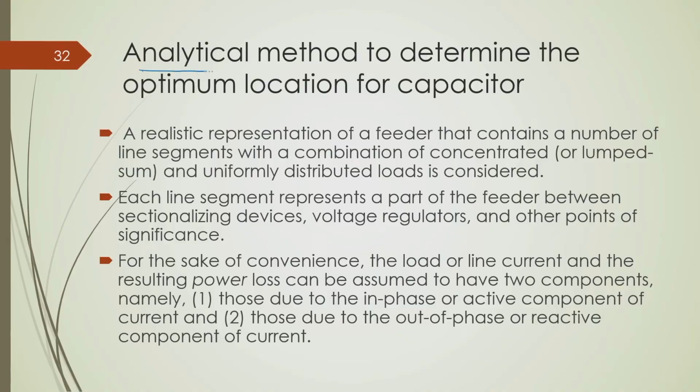Now, in the next few slides, or the last part of this module, I will discuss an analytical approach to determine the optimal location of the capacitor. As I said, the determination of the optimal location and size of the capacitor, and how many capacitor banks I should install in a particular distribution feeder, is usually done by formulating an optimization problem and solving it.